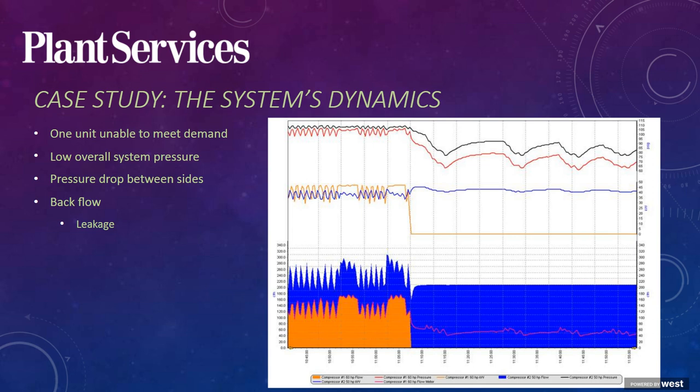So why do both air compressors need to be online and loaded? It's a good question. When we look further on the same chart, where number 2 is loaded by itself, but pressure is falling, we also see that there's a significant pressure drop between those two rooms when compressor 1's offline. It's between about 10 and 15 psi, suggesting that the piping network, remember we identified that as 1 1/4, 1 1/2, and 2 inch, significantly undersized.